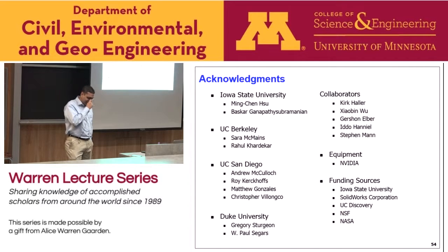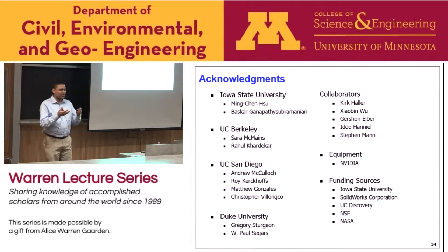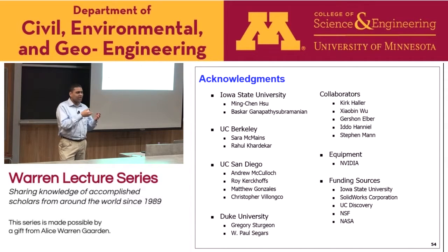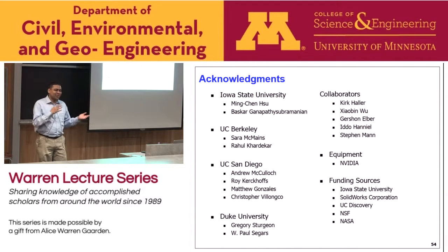But one of my students is working on it. In terms of finite element analysis, you usually have two steps. The first one is the element stiffness computation. And the second step is assembly and solving the global stiffness. The second part essentially leads to a matrix inversion operation, and apparently other people have found that it's not that fast on the GPU.